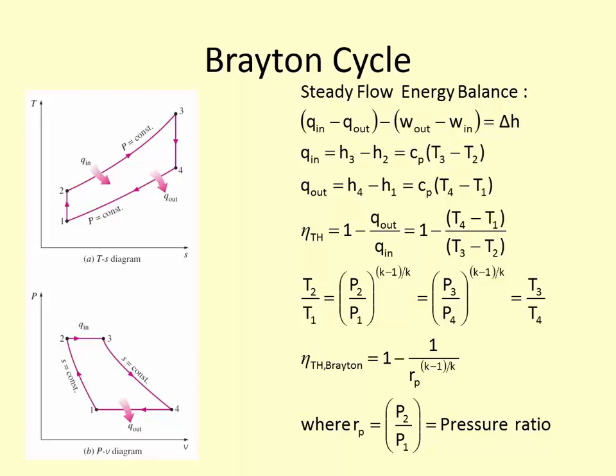If we're using a different gas and making the same assumptions for an ideal gas, but instead of using air, we're assuming it's something else, mostly methane or whatever it might be at a very high temperature, then we would use a different k value.